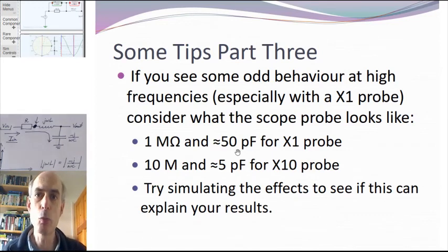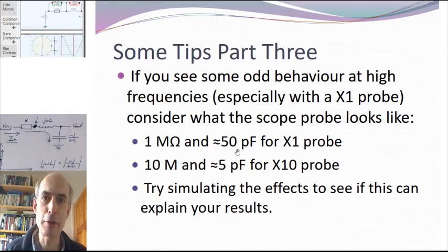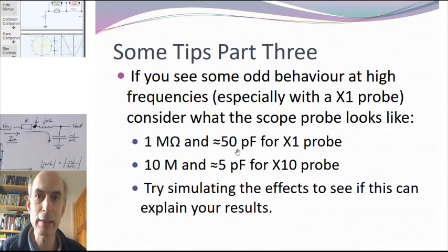So if you're using one of the breadboard utility thingies, then don't use the probes with a length of coax cable attached to them. As soon as you connect up one of those to your circuit, you are in effect adding several tens of picofarads to your circuit, and that can disrupt its behavior. So, ×10 scope probe, and connect it directly to the leads of the components that you're trying to measure.